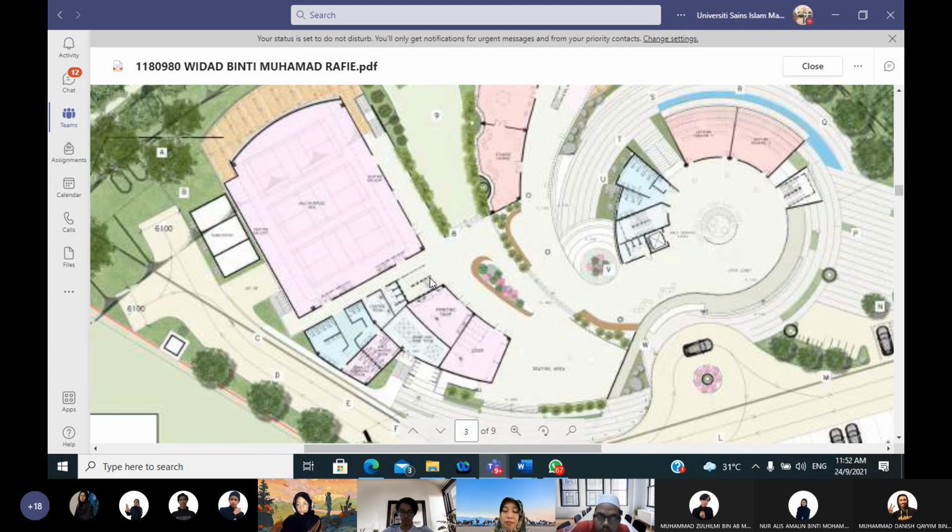So 45 is the maximum. But what happens between 45 and 61? Let's say 50 meters. So at 50 meters, you need to provide sprinklers; this is considered a sprinklered building.